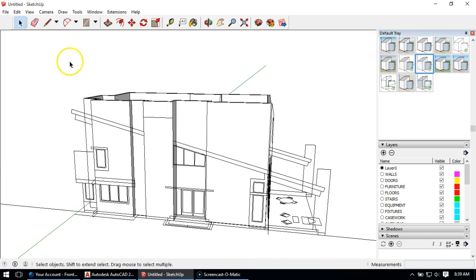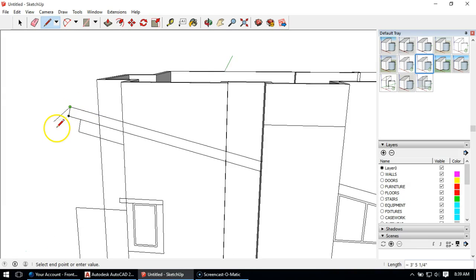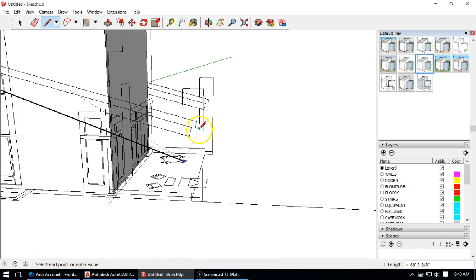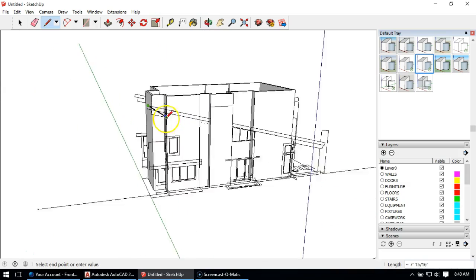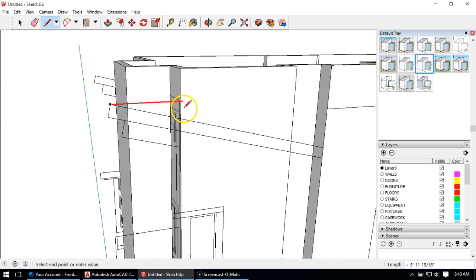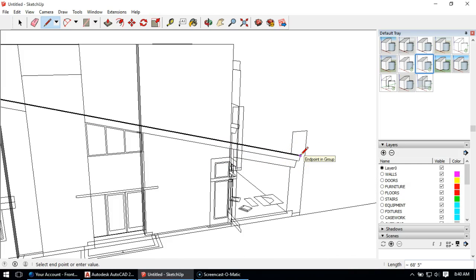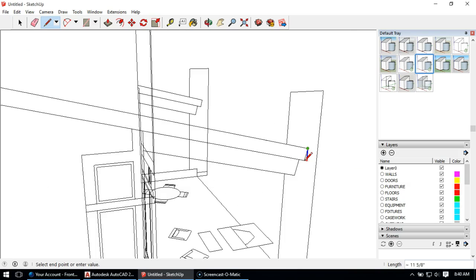So the thing I'm going to do first is start by modeling the roof plane itself. This is where I'm going to use my scaffolding from my elevations. I'm going to go to my pencil tool and trace out the extents of this roof, not the beams, which are these lower elements here. I don't know why I'm not snapping on that corner here. I got locked in on a direction there. There we go. I'm just pressing my arrow key to reset the direction, so I've pressed it twice to get reset there. If you're having a similar issue, it's a little trick.